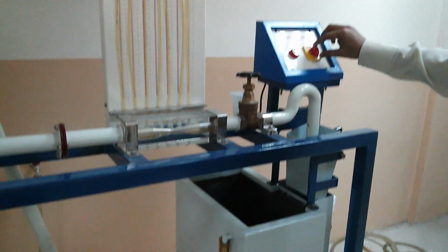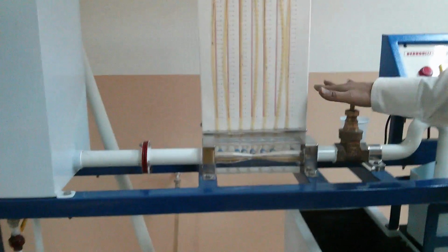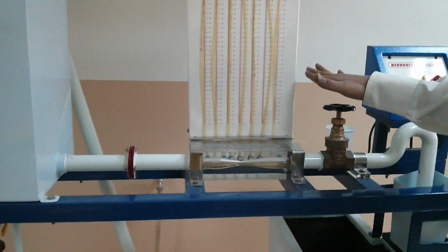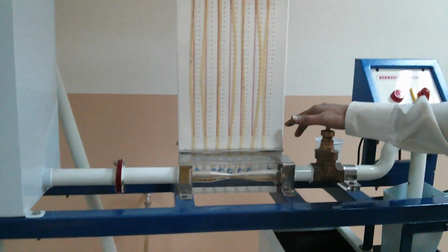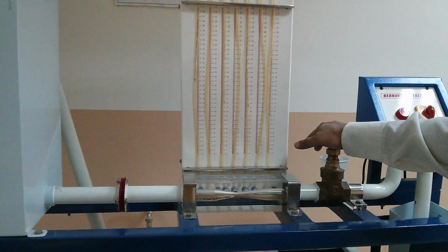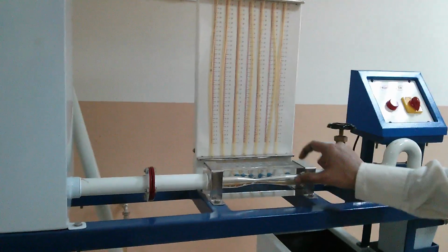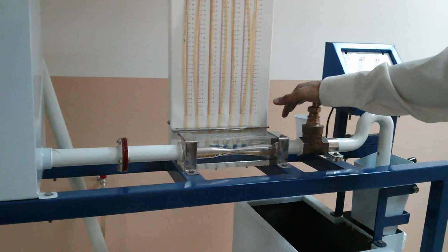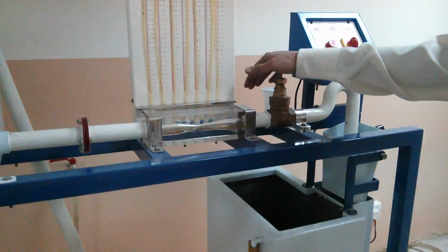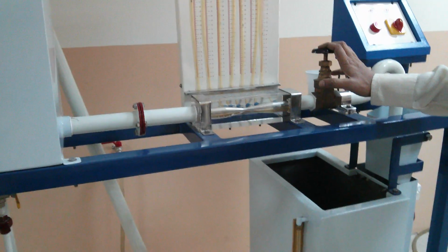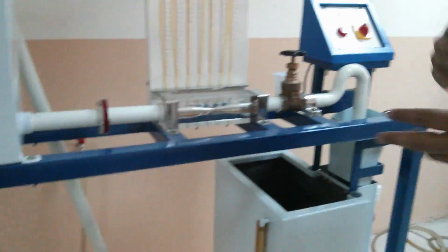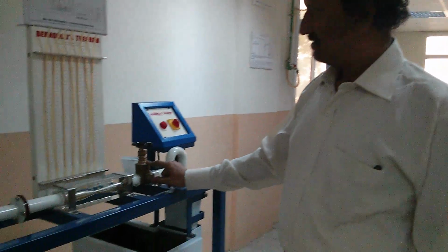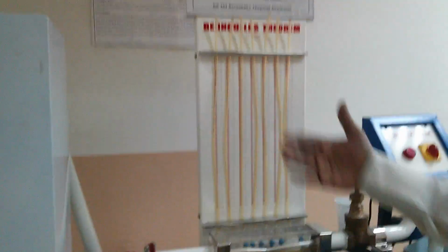So to start the experiment, you have to switch on the pump, right? Set the valve at a particular position. By that you are setting the flow rate, right? Once the flow rate is set, you measure the piezometer readings at different locations. Suppose you are asked to do the experiment at 3 or 4 different flow rates. Keep a minimum flow rate, then go on closing the valve, so that between the minimum and maximum you have some 4 flow rates. At each flow rate, wait for some time, and once the values in the piezometers become steady, note down these values.